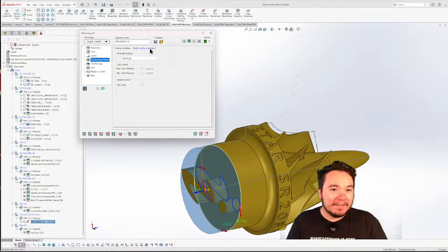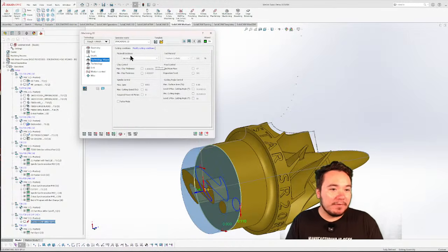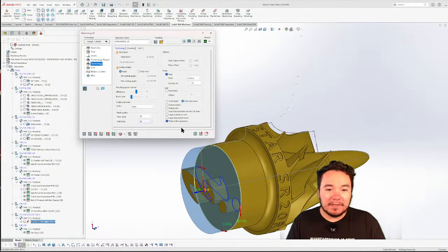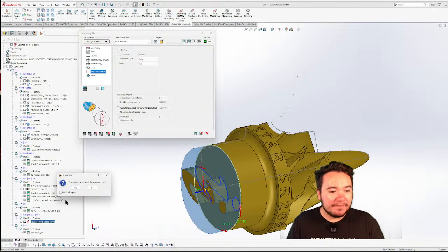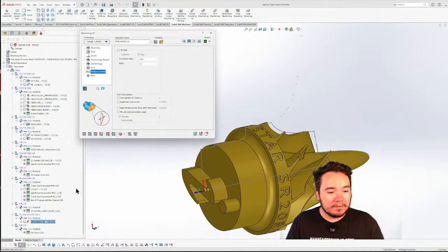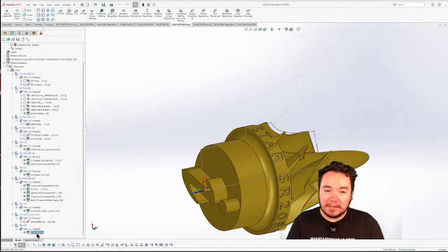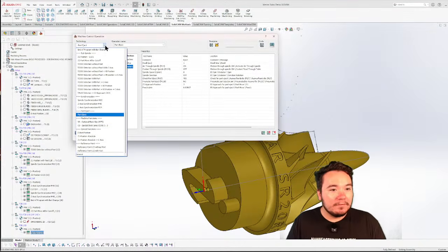It's pretty impressive. Cutting parameters, I didn't mess with anything there. I did do finish entire geometry, give it an Ra finish of 16. I pretty much left everything pretty basic here. So just your normal iMachining 2D operation. Exit. Okay, and then at the end, just added another MCO. Part eject. Simple as that.